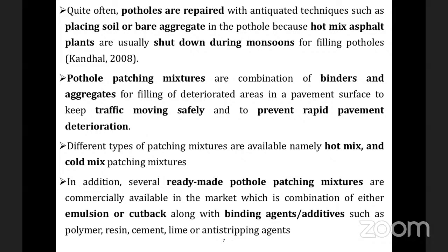Mainly, different types of pothole patching mixtures are available. One is hot mix and one is cold mix. In monsoon, we can't go for hot mix; in monsoon, you should go for cold mix. So what is cold mix? Cold mix means the mixtures which are prepared without heating the materials. Hot mix means the mixture of binder and aggregates which is prepared at some mixing and compaction temperature.